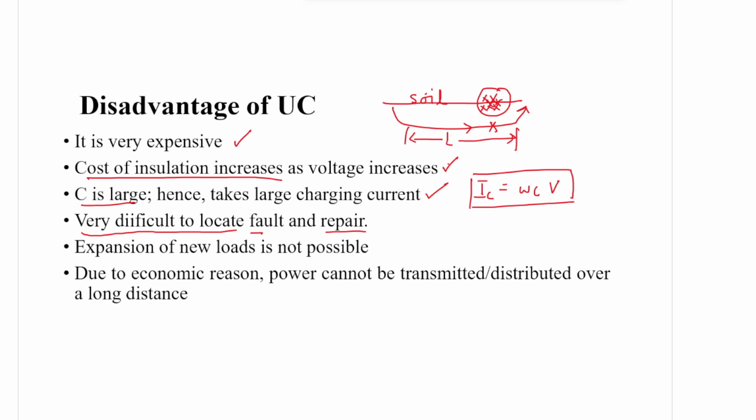Another point is that expansion of new loads is not possible. Let us say today my load is 100 ampere. Now if it needs to increase by 50% to 150 ampere, with the existing cable configuration it is not possible. You need to erect a new line for the extended load.